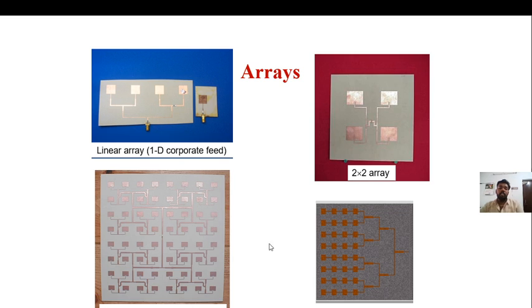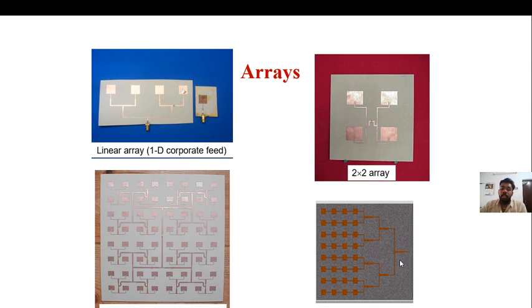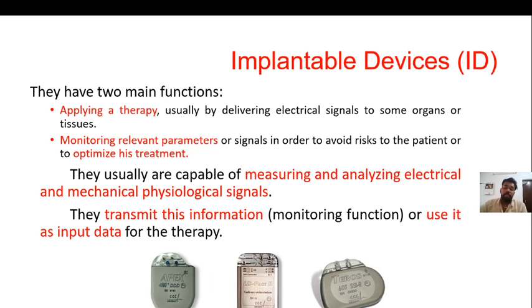And this is the fabricated design for some of the arrays. You can clearly see the microstrip feeding and quarter wave microstrip feeding have been used widely in order to convert it to an array, since it is easily designed and fabricated. So up to here we have seen some basic concepts about the microstrip patch as well as some feeding techniques.